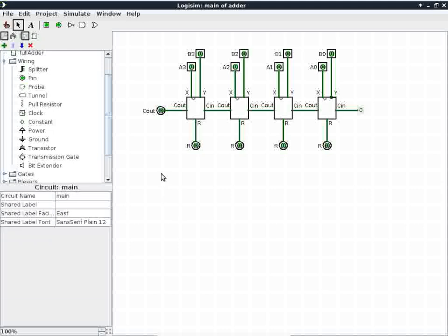And you can label the R bits too, R0 to R3. Okay, so now we want to test it, right? Just because we got the half adder done correctly and the full adder done correctly, it's not enough reason to believe that this overall design is working. So we want to come up with a 4-bit by 4-bit addition and make sure the design is actually working correctly.